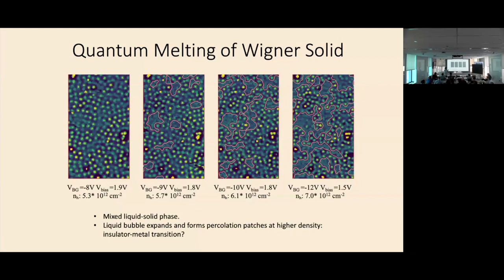Given the electron density over here, the electron-electron separations are all 10 nanometers or smaller. So we think the gate effect is relatively small. It's not very strong, but not negligible. In the future, once we have a good handle on this, it will be good to have even thinner BN, so you have a stronger screening effect and can really do a quantitative study of what their effects are. Right now they're relatively weak, but maybe you can say they are still present.